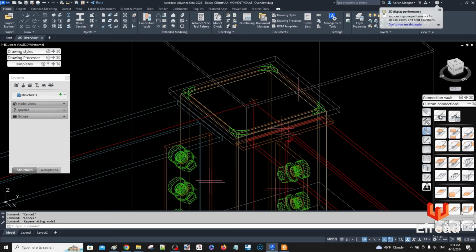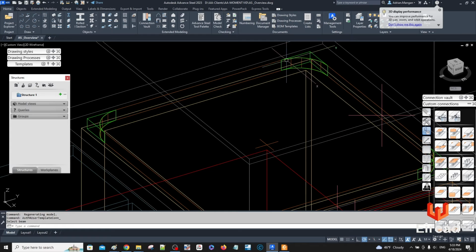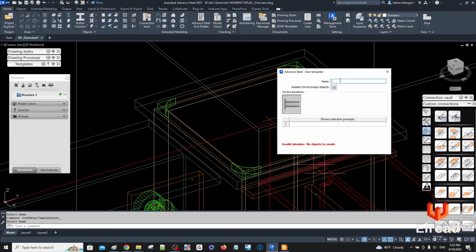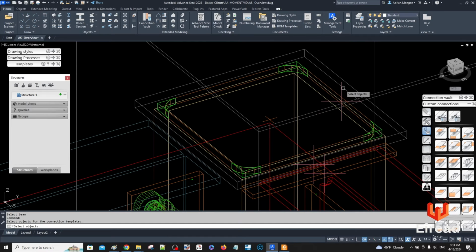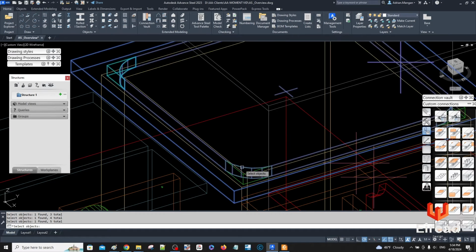So what I want to do is create a custom command. It's one beam at end, and I want to, oh, I never selected the beam, sorry. One beam at end, select the beam, post cap, column cap, I guess, HSS 8x8 cap. Objects. I will select the box just to be safe. I'll select the weld, I'll select the plate, and there is no feature cutting the column, so I'm just going to select these.